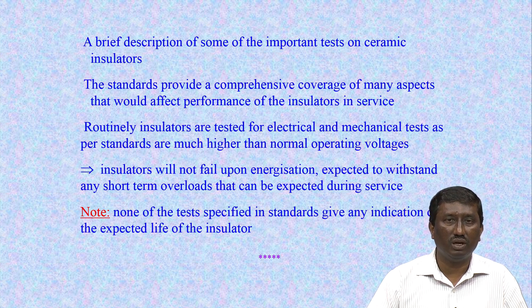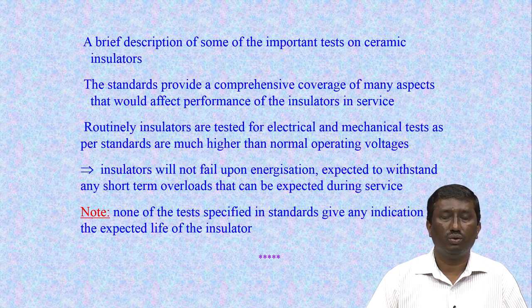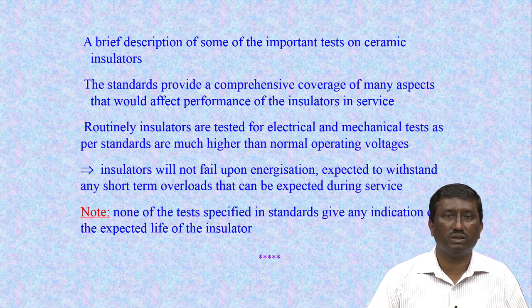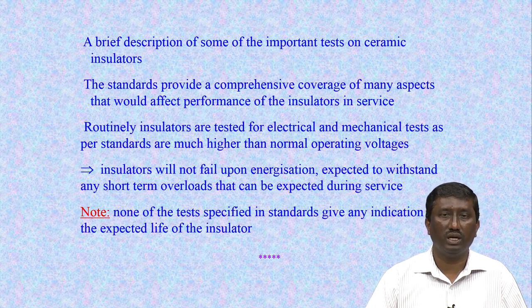So, the tests which have been described till now concern the various porcelain or glass type insulators which are used from lower voltage to very high or ultra high voltages. Now we will focus on the polymer insulators. These polymer insulators, as mentioned earlier, are of recent origin and are organic in nature. So, this requires, apart from the tests which have been mentioned, some other tests. Some of the tests have been standardized and some have not yet been standardized.